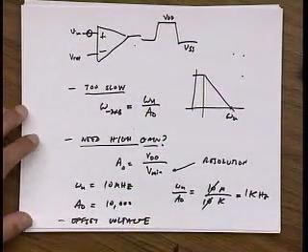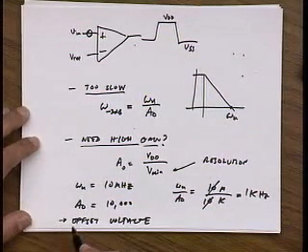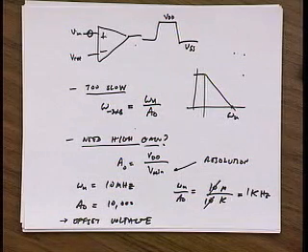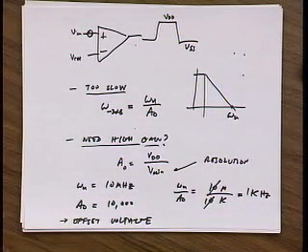And actually, it may not be obvious at this point, but in answer to your question, this is why we don't use positive feedback. Because generally an amplifier with positive feedback is going to have a large offset voltage. But we'll come back to that.